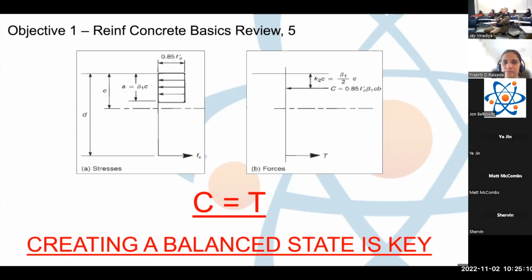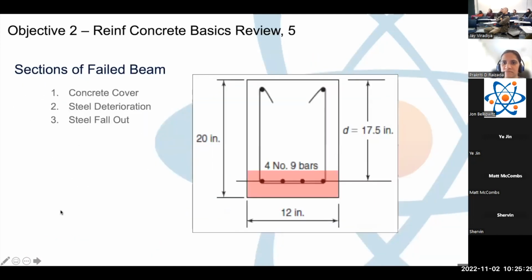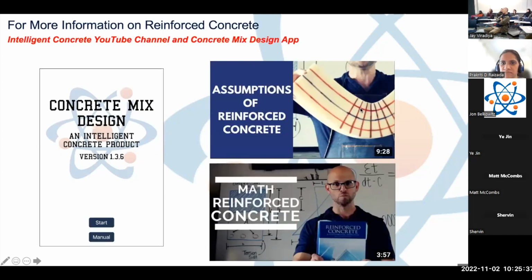So when you look at a concrete beam, and I'm sure your professors have done this, where they take a foam beam and they bend the foam beam in half and they make the foam beam smile. So you have a beam of foam and it's smiling, and they usually draw squares on it. You know what? I have a picture of this. Hold on, let me get to that picture. You can see that the top of the, there it is. So the top of the beam, the squares are squishing, and the bottom of the beam, the squares are expanding.